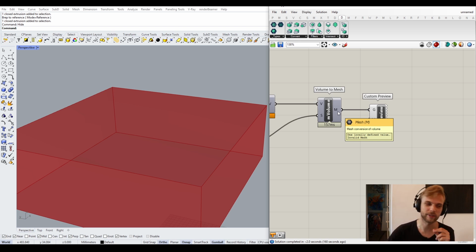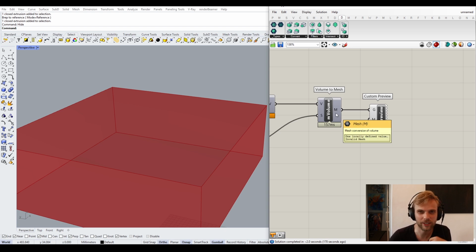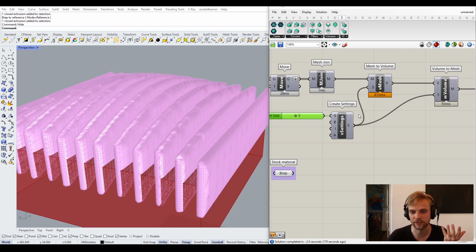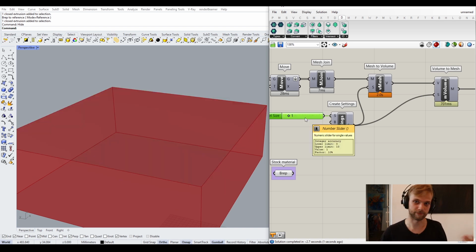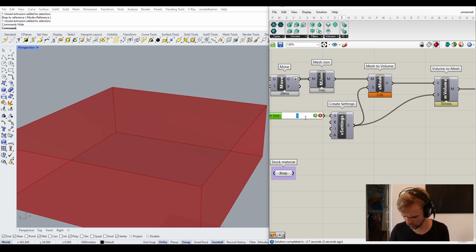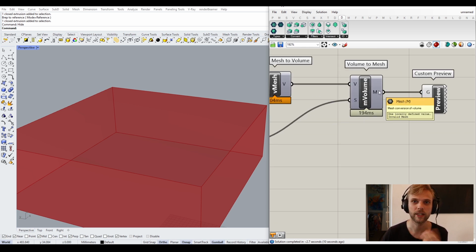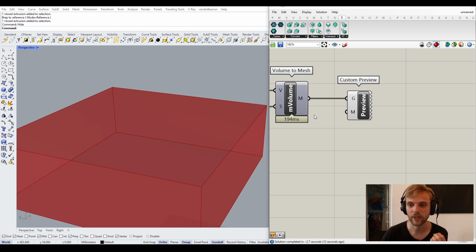So Dendro, this actually is a good segue. Dendro is not that stable, right? It tends to break quite often, and only certain values work. So you can see 3 millimeters works, 2 millimeters didn't work, 1 millimeter might work, might not work, who knows, doesn't work. So I'm going to actually use 2 millimeters here, and I'm going to see how I can make this invalid mesh into a valid one, right?